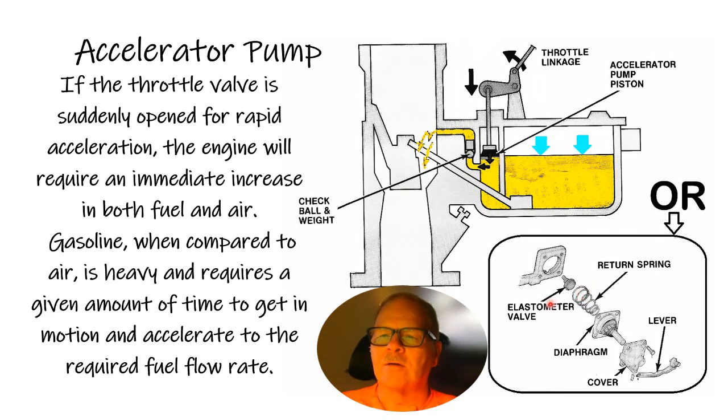But the accelerator pump, well, if it's not working, it'll stumble, fall on its face. Also, that accelerator pump, when you're first starting and setting the choke, it squirts some gas in there and wets the manifold. Even on the fuel-injected engines, you still have this function because it double pulses the injectors when you're starting it cold. That's just the way it is. And so, get used to that notion.